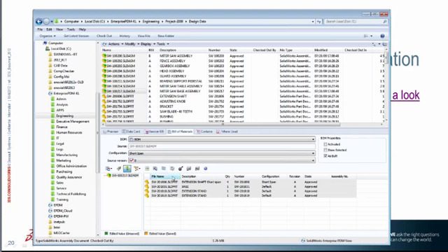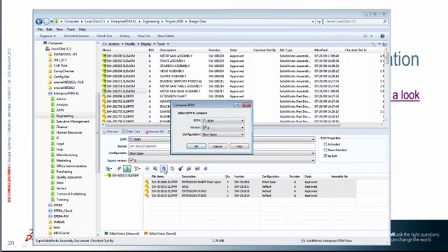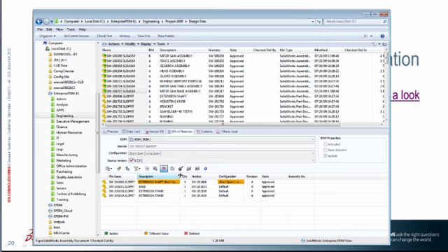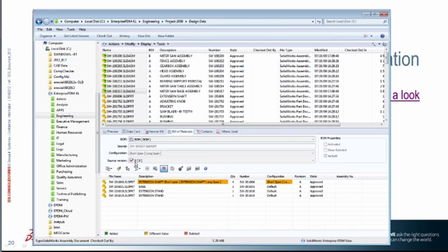Now let's say that this is a small assembly, and it's easy to see what the changes are. But if I didn't have that luxury, I could use my compare. So in this case, I'm going to compare my short span to my long span to see what the difference is, and Enterprise PDM shows me exactly what changed between those two versions. My source version is the configuration short span, and it's comparing it to the long span. So this shows the value of what's in the long span compared to what's in the short span, and it highlights it with an orange color. If something was added or deleted between those configurations, it would show up as well with other colors.